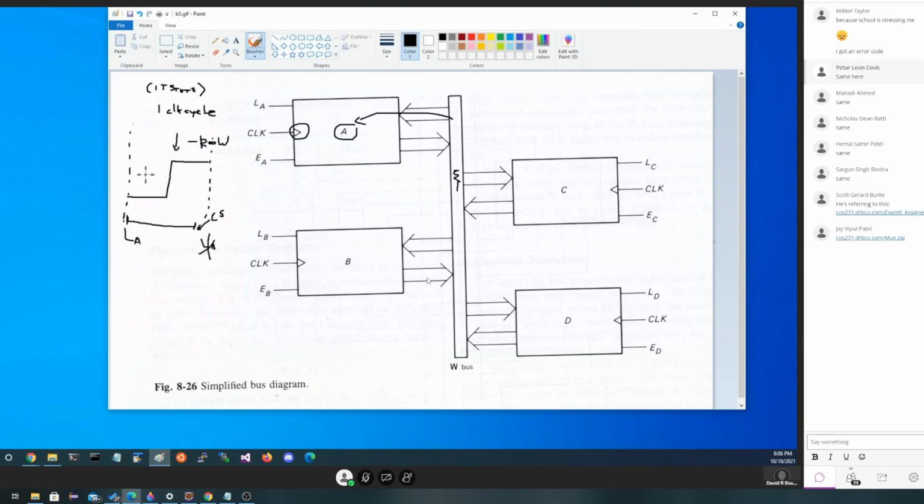So this timing of when things occur is very, very critical. And we control it by using control signals at the start of the T state on the low clock, the 0 of the clock. Data gets transferred on the 1 of the clock when it goes high. The low signal is held for the entire T state, and it changes again on the next clock cycle. So let's move some data around here. Let me erase some of this.